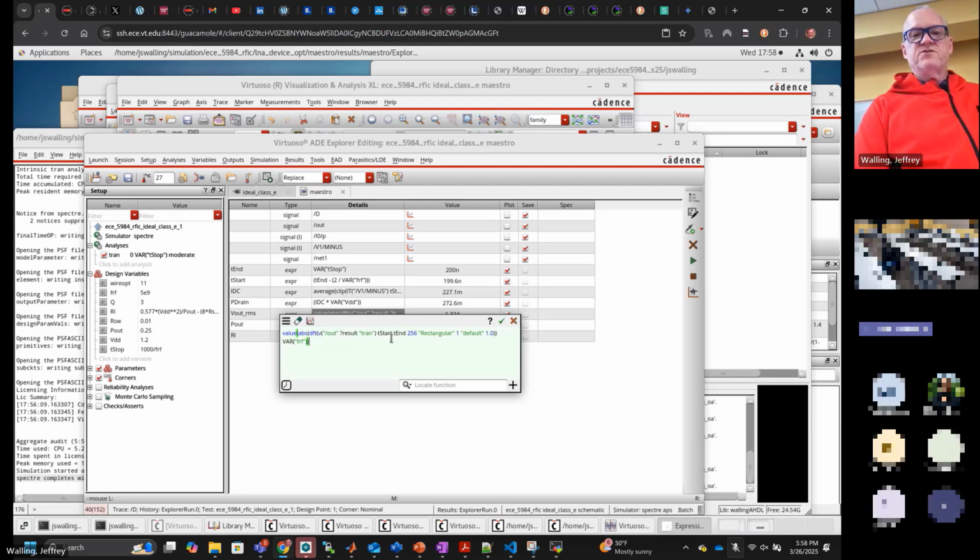So that's what the function is designed to do. It applies a rectangular window in case we do accidentally do that. That'll help the analysis, and then it finds the value at a frequency. It linearly interpolates the value at a frequency of FRF. So this DFT is going to put out a spectrum, and I just want the fundamental component.